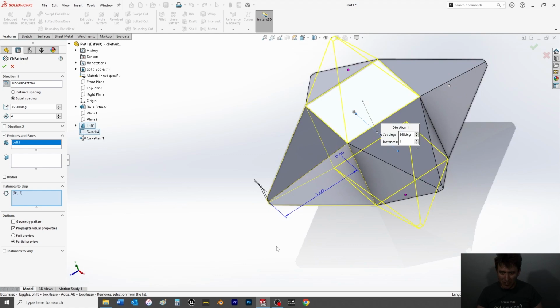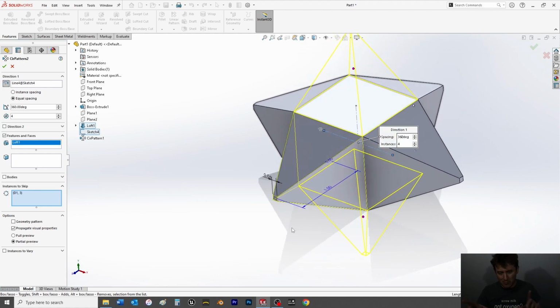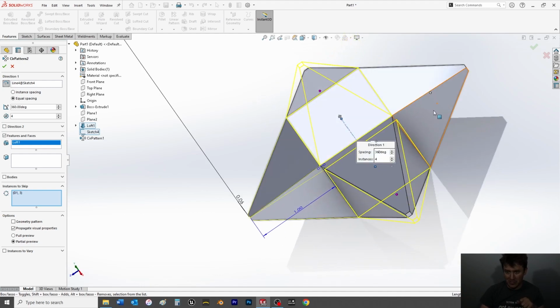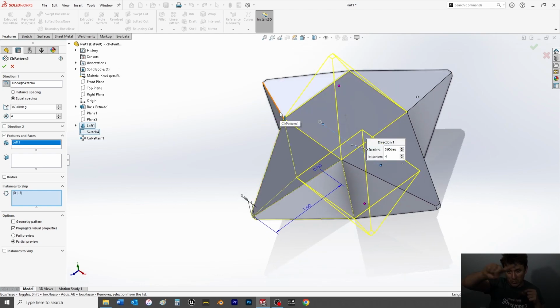Because there's a spike already there, and if for some reason this original spike changes, or say the vertical rotating instances change but not the horizontal rotations, in other words this spike here, if this were to change for some reason, you may not see that reflection if you did not omit the instance on this horizontal rotation because it's covering over it. So that's why we're going to skip it.